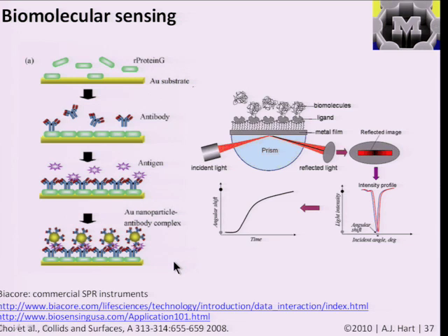And another modification upon that, or a modification that might increase the sensitivity, is to not only bring in the PSA, but, for example, have a step before that takes your solution with the PSA that you're interested in and attaches it to gold nanoparticles. And then you can bring in the nanoparticles with the PSA on them, and those will kind of further amplify the signal that you get by this interaction. And so then you imagine bringing one gold piece next to another, and then you can get perhaps a more sensitive sensor.